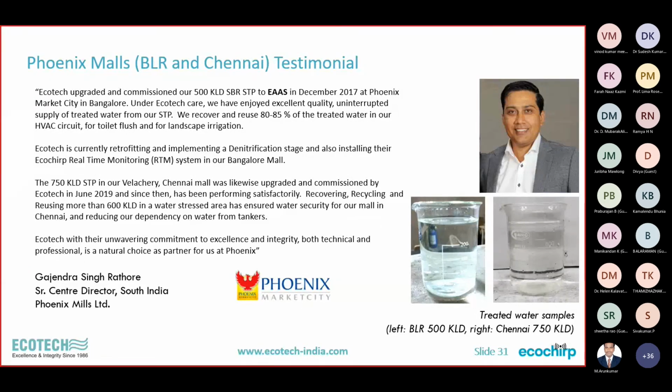Since this was a presentation we gave to Phoenix malls, this is what we get. This is the quality of water we get in Phoenix Mall, which we are operating for the last 4 years. You can see in this mall, it's a 500 KLD STP. We also have a softener at the end of the treatment to generate soft water for use in their HVAC circuit, the cooling tower circuit. And we maintain a hardness of about 30 to 40 ppm, which is what is required in the soft water to be used.